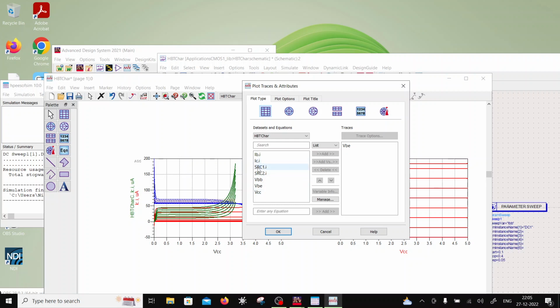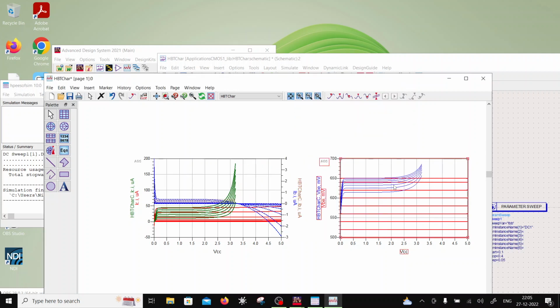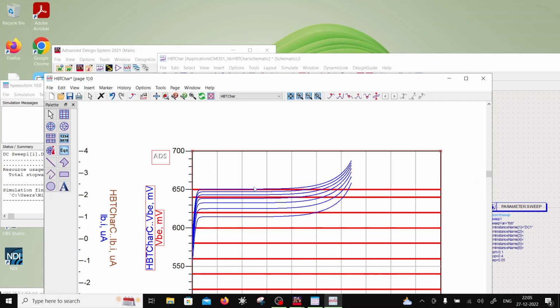resulting in avalanche breakdown. So let's see, from this, let's see VBE. So now you can see that VBE is flat because the collector base junction hasn't gone into breakdown, and the minority carrier density at the base emitter junction is fixed because of the base current, right? And that's the slope is fixed, right? And that's why the collector current is fixed.